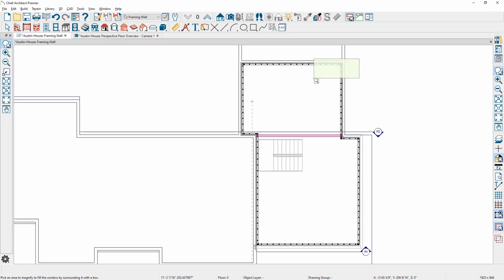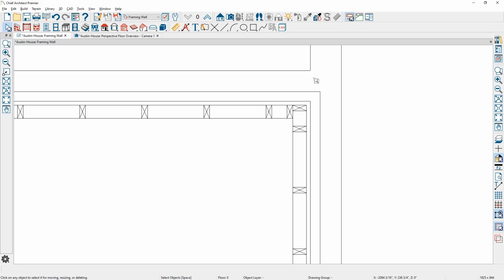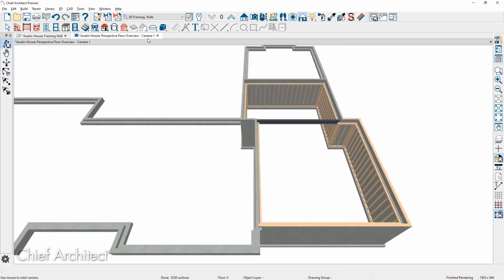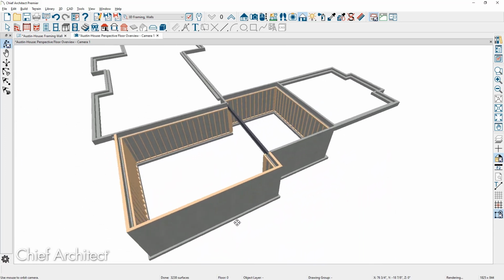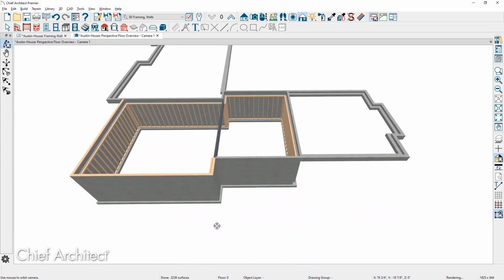The reason, because I have a complicated foundation and wanted the control over the framing structure, given that my foundation is stepped and I also have a hung platform, and I want to make sure that it was correct. The disadvantage is that I had to draw two different walls and then position them. In the end, I wanted a more accurate approach, and this worked best for this project.